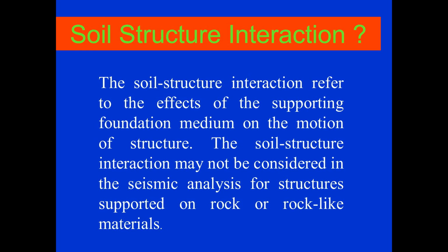The various criteria related to soil structure interaction, their assumptions and various tables are available in IS 1893. We will see step by step. Soil structure interaction refers to the effect of the supporting foundation medium on the motion of the structure, and it may not be considered in the seismic analysis for structures supported on rock or rock-like material.